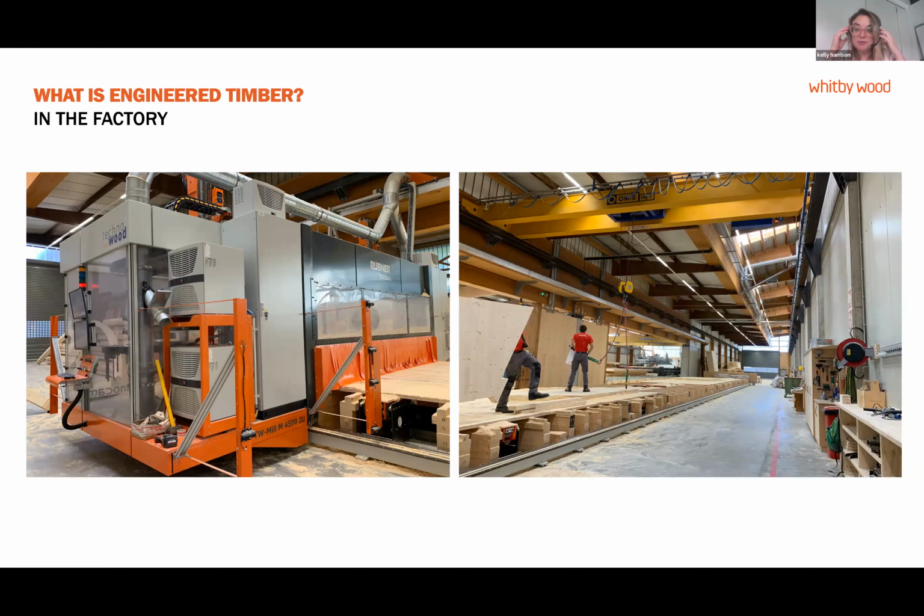Or if you've got a hybrid project and you're looking at, say, a concrete core, which may have a 25 millimeter tolerance zone, and you want to connect some very precise beams into the side of them, or columns to the same height, then you have to think about those connection details and ensure that the differences between the two types of material are really captured at the beginning, because again, I've been caught out by that in the past.